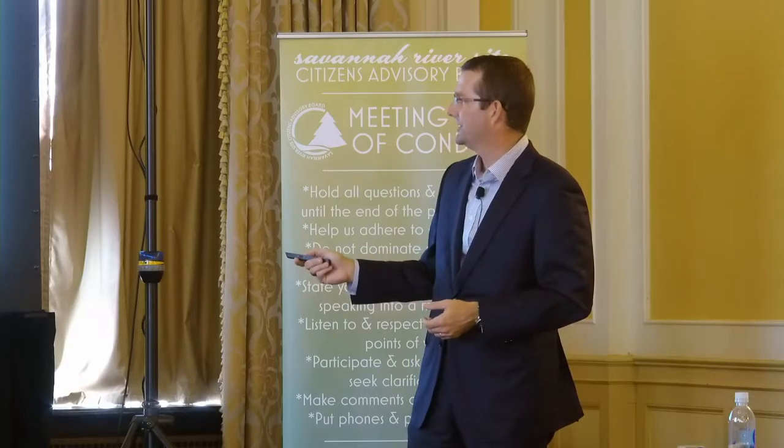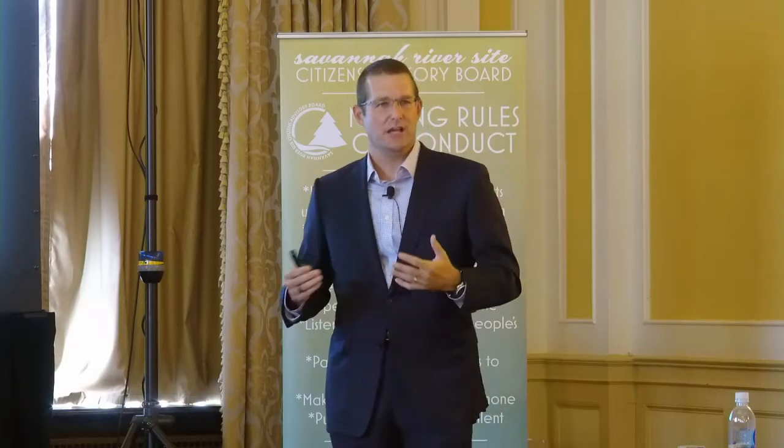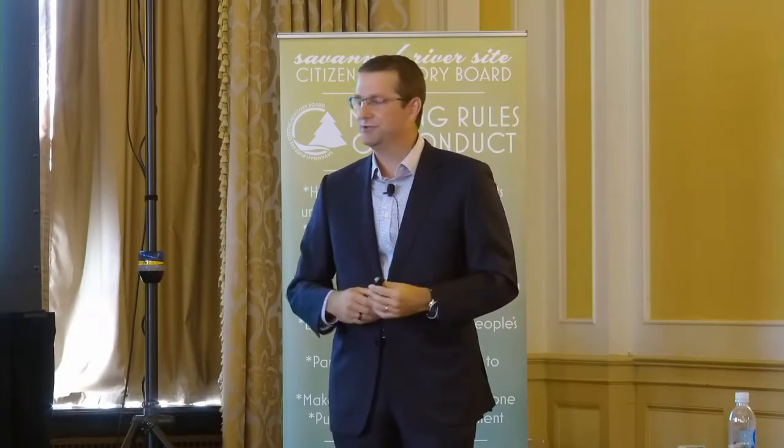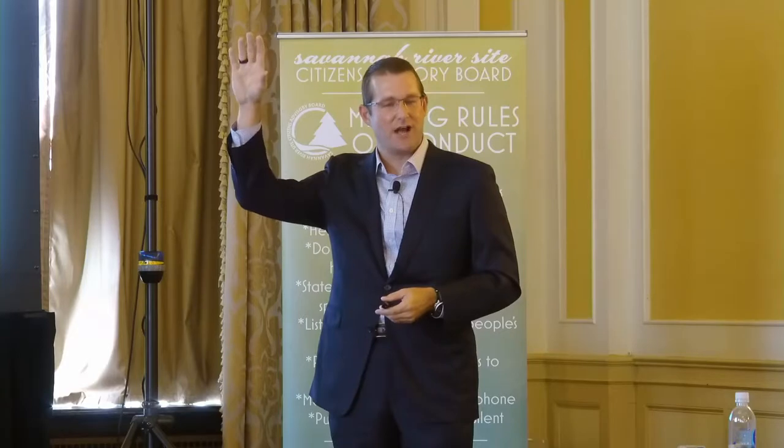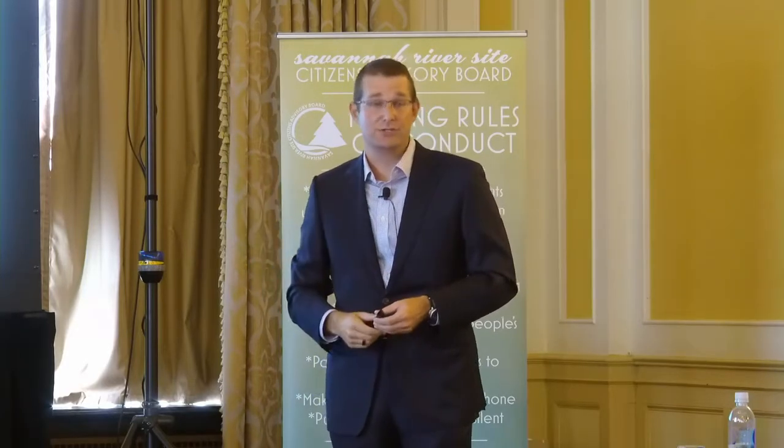I put as an example on here an upgraded dust collector. We have dust collectors anywhere we have dry material because we operate under an air permit that doesn't allow us to discharge this stuff to the environment. And the original dust collector was sized to accommodate 1 truck. The material comes in on tanker trucks. It is pneumatically blown into the top of the silo. The dust collector has to be able to evacuate all that air. The original one was only big enough to handle 1 truck. Again, at the lower throughputs we've been experiencing, that hasn't been an issue.